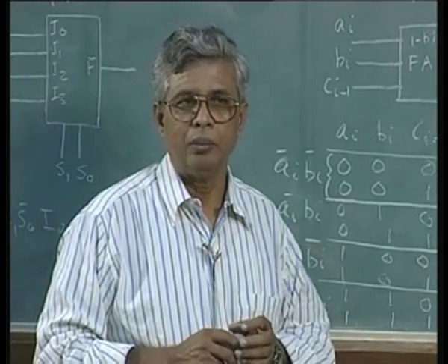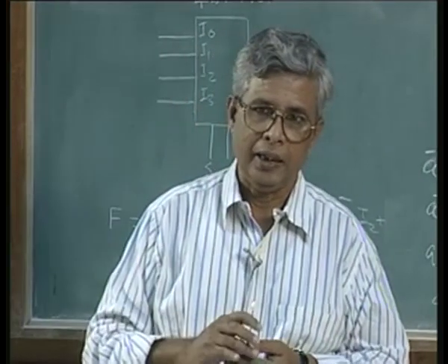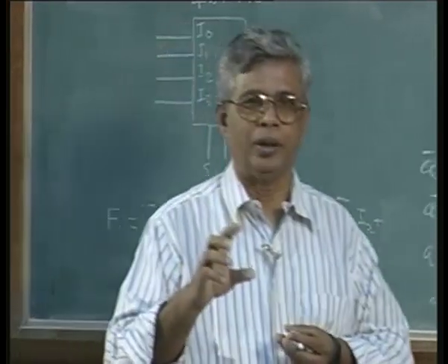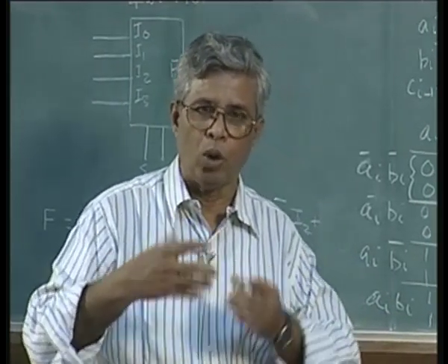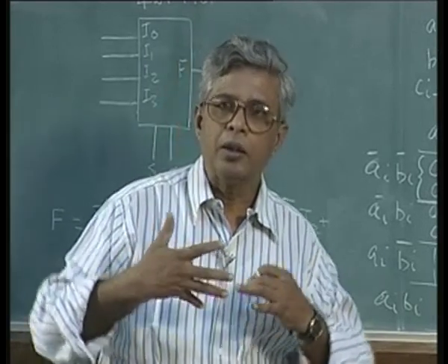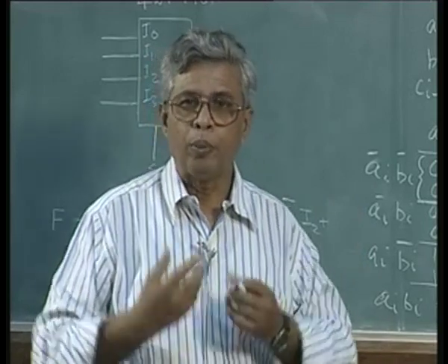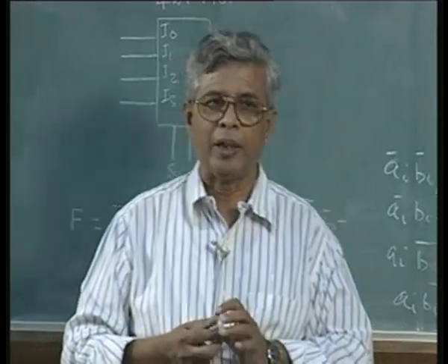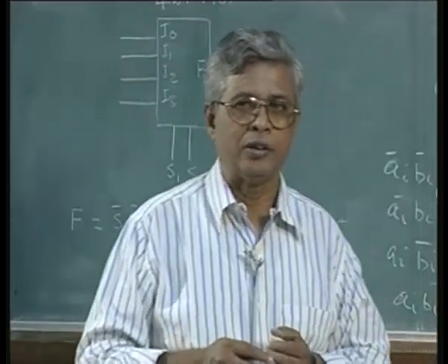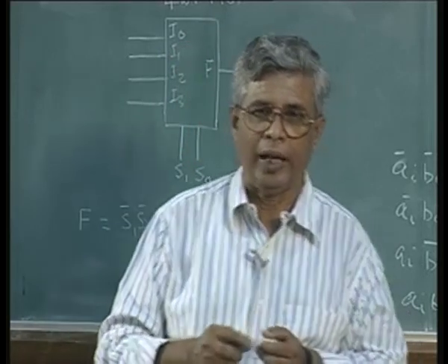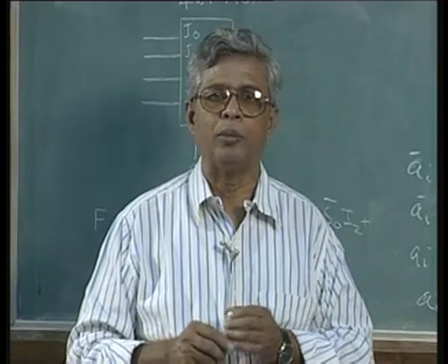As an example, I took a multiplexer and a full adder, so that the concept is clearly understood and it is also simple. Think of this as a bigger and bigger problem. As the problem grows, we can get more and more complex circuits using multiplexers. It can be proved, just as we proved in our earlier combinational logic course with gates, that all logic functions can be implemented using AND, OR, inverters to start with, and further simplified to NAND gates and OR gates. It can be proved that all the combinational logic can be derived using multiplexers.